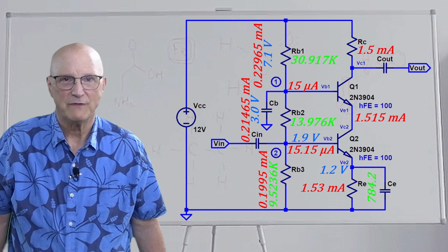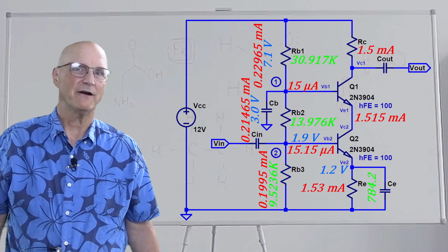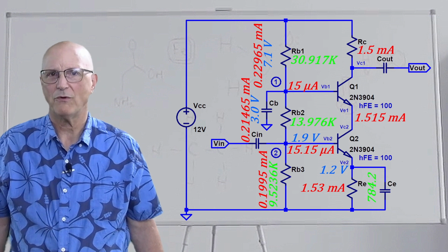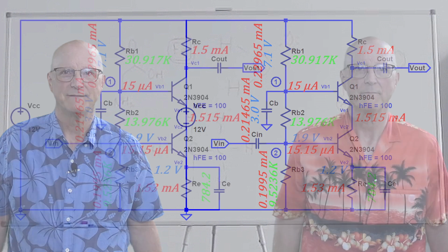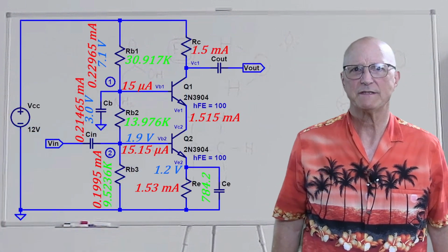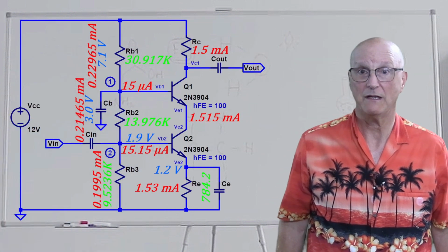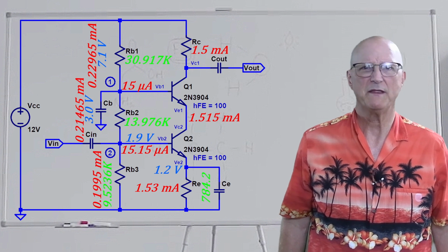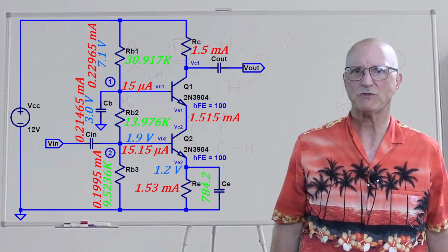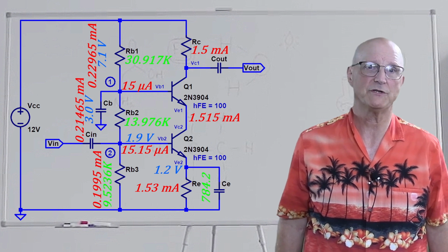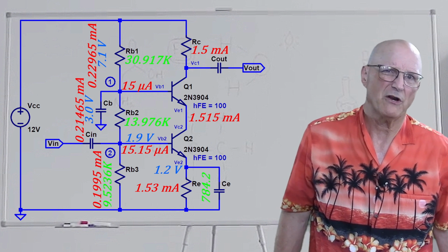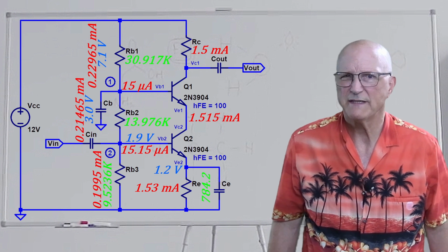With this conundrum dissipated, we can now turn our attention to our last unknown component, the collector resistor Rc. Our design criterion says that the quiescent voltage on the collector of Q1 must be in the middle of the available voltage swing with Q1 and Q2 in their linear active region. So how do we determine what this available voltage swing is?